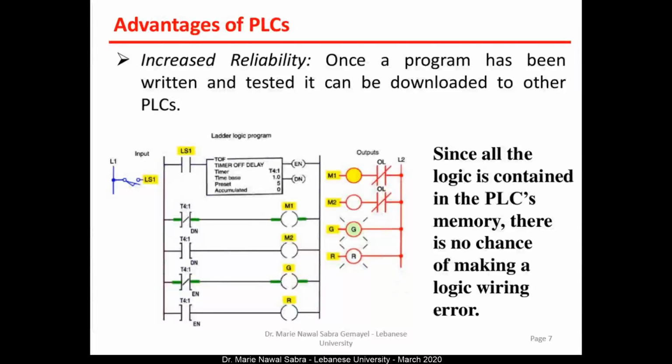Plus, when I am wiring a relay, I have a lot of problems when a wire doesn't fit correctly, and here we have a much reduced problem of wiring because the wiring has been reduced to only the inputs and the outputs of the PLC.